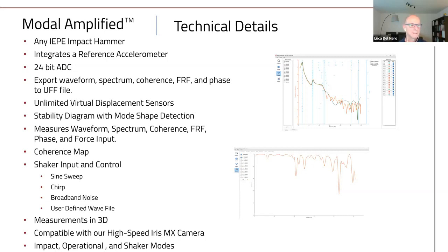Okay, and moving to motion amplification, this became totally different. So you can do a shaker test and discover that maybe your first natural frequency is not related to your component, but simply to the fact that the fixture, the connection to the shaker, must be done with two or three more screws. Okay, and this is something that happened.